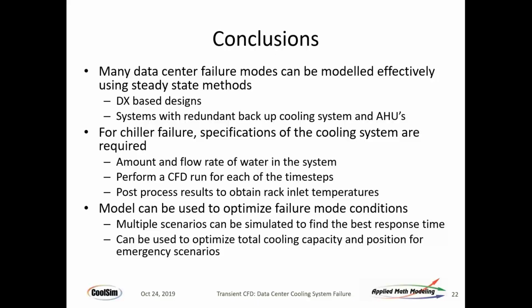This is also the same case if you wanted to bypass the chiller and go to the cooling tower. Same exact case, but the ramp would be different, because going to the cooling tower or some other device will change the rate of increase. And it's even a function of the time of year. If it's winter time and you're using a cooling tower, maybe you don't need to worry about much because you've got enough cold out there. You've got an infinite sink, effectively, of cold air to dump the heat to. These things will all affect the transient analysis of the data center. So it becomes more of a systems approach, a systems analysis, to be able to figure that stuff out.